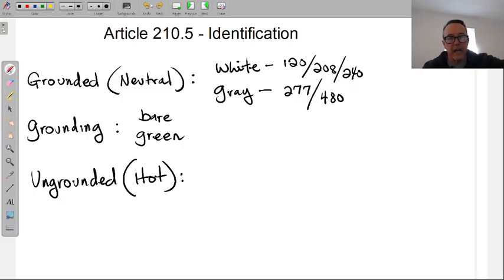Now, this does not affect the motor, the life of the motor, or anything other than the size wires that I use, and the breakers that I have to use, and the size conduits that I have to use. The higher the amperage, the larger the wire, larger the breakers, larger the conduits. More expensive. So when you have to put up a lot of motors, or you're building these large commercial buildings, they'd rather 480. But if you're a commercial building, as I said, you also need low volt, you need outlets, you need to plug in computers and have standard 120.